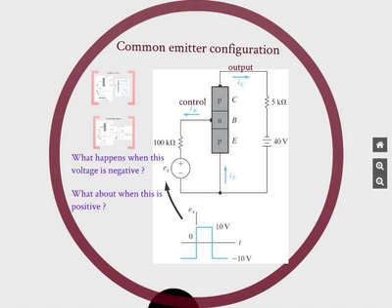So the ES shown here is the voltage input, which can be a switch, 0 and 1. And there's a load which drives the current. So when you apply different voltage, the current changes. As the base current changes, we know now that the output, which is the collector current on the top right, will modulate. So that's the switch.